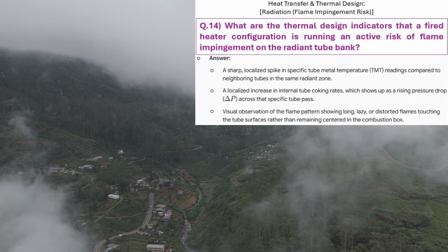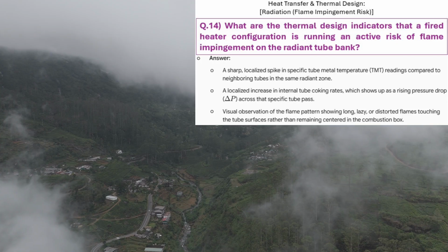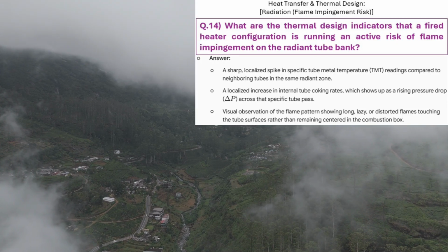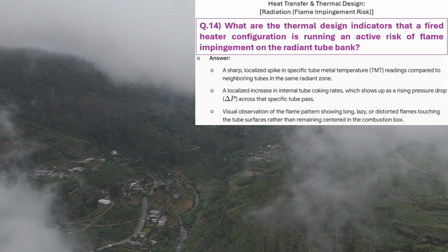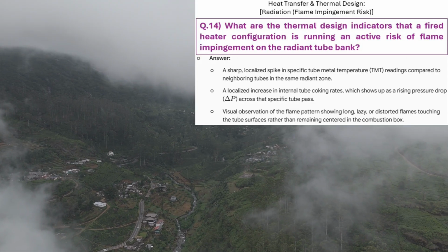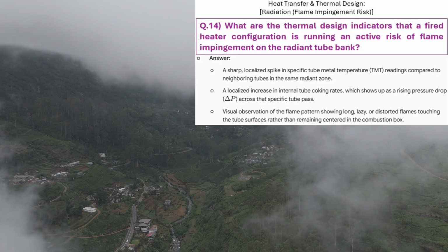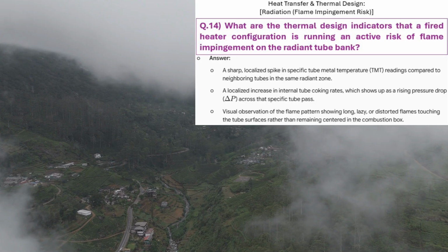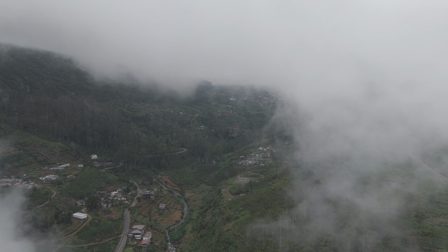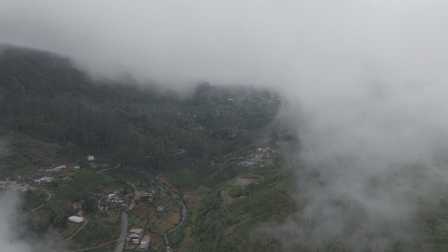Right, and I always specify real-time infrared flame scanner loops to trip the gas if spatial distortions occur. A critical caution for the observers: blending high hydrogen streams into fuel gas massively increases flame speed, which fundamentally alters the heat flux distribution, shortening flame length but intensifying localized basal heat flux, catching operators completely off guard.